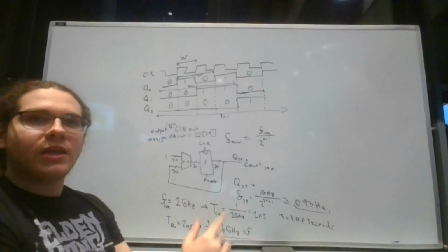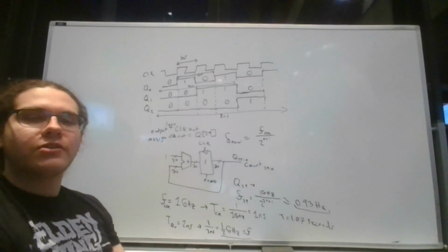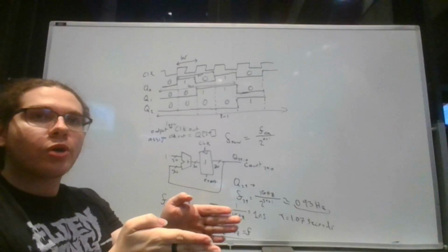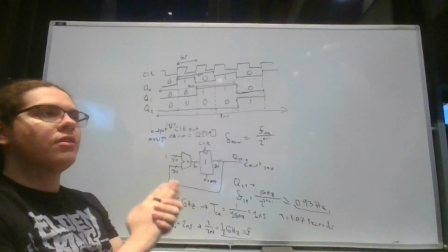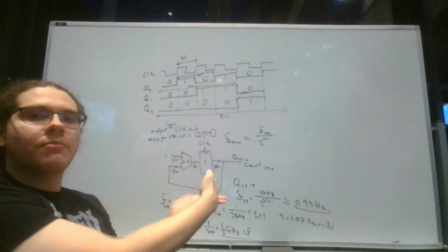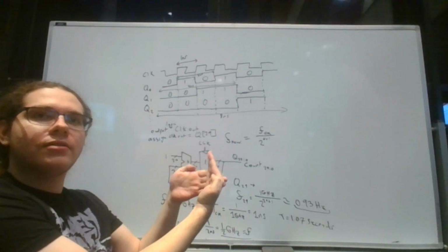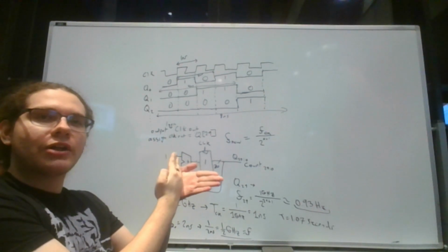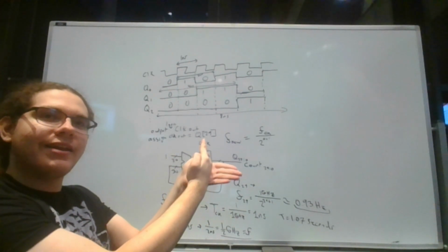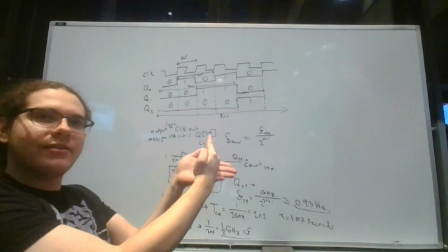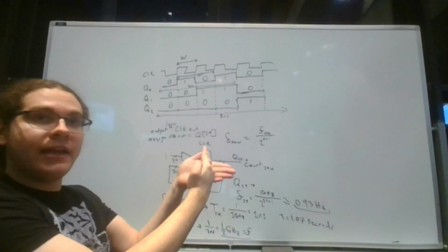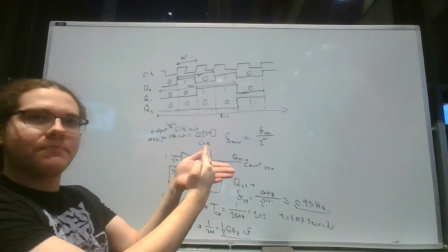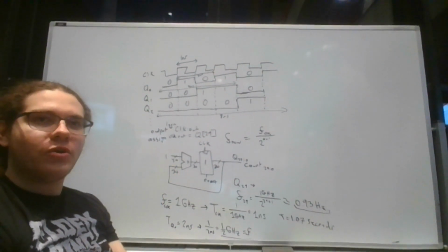That happens because of temperature differences or voltage variation in your supply. So the designers purposely limit the clock. They say, theoretically, here's my 100% mark, the fastest I could possibly run my clock, and I'm going to put it at 80% of that speed. What overclockers do is push it up to 85, 86, 87%. And the system's still running fine, as long as they keep it cooled well enough. They have to do lots of cooling, like water cooling. So that's why you can overclock a system.